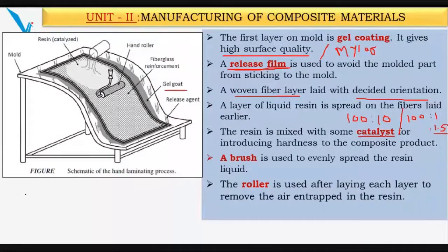You have to mix this in proper proportion, and ensure that it will not get cured before you make the finished product. So you have to manage that time, and accordingly add the hardener or accelerator. If you add it in less quantity, then the curing time will increase.